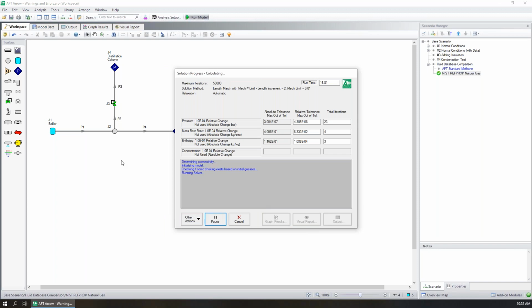So we'll let this continue to run just to prove a point: if you're troubleshooting and you're waiting minutes between runs, then the return in runtime is worth the trade-off with accuracy. And you might be able to simplify your fluid, and that'll speed up your iteration process. So again, just with that 6-component mixture, not too complex. We'll take a look in the next section at how that'll impact your results.